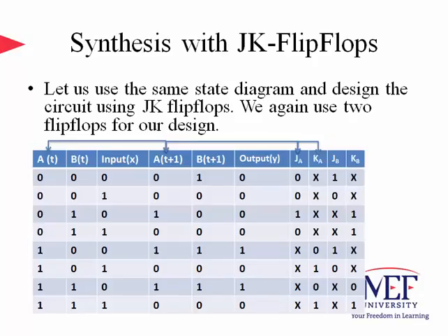The design with JK flip-flops follows the same steps, except we need to use excitation tables to derive the input conditions for the J and K input terminals of the flip-flop. Let us use 2 flip-flops for our design. You could use more flip-flops, by the way. It will increase the number of states in our system, although a subset of them would not be used. I recommend trying a 3 flip-flop design yourself to get a feel of what's going on.